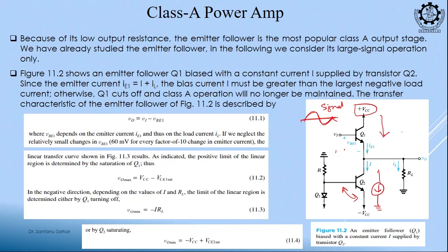So, in this kind of circuit you always look for the input signal is connected to which terminal. So, that is your main driver. The other one is connected to a fixed potential. So, this is a DC circuit, DC input. This is for biasing. Most of the time you will be seeing that it is used as a constant current source. So, you can think of a current source having current I.